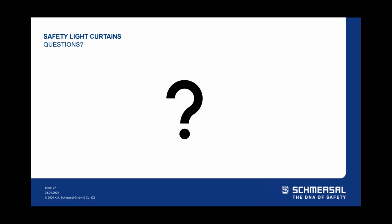Do you conduct on-site visits to help companies determine if a light curtain will work, and if so, which one? Yeah, so again, we just discussed it, and not to speak out of turn, because I know Devin probably goes through this type of thing in his webinars, but when you do have a third party come in, if you did have Technicum come in, then you have that information. You get an electronic copy and a hard copy, and now you have documentation of what you've done: that you've done a stop time analysis on the equipment, and a safe distance calculation to make sure that you have installed your light curtains correctly and they are in the right place. So yeah, good question.